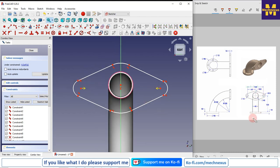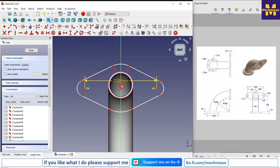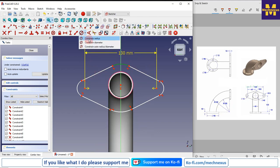Now the center to center distance is 130. So I will select this point and this point, and I will give it 130. Now this radius is 35, so I will select this and I will give my radius 35, and I will make this one and this one equal.